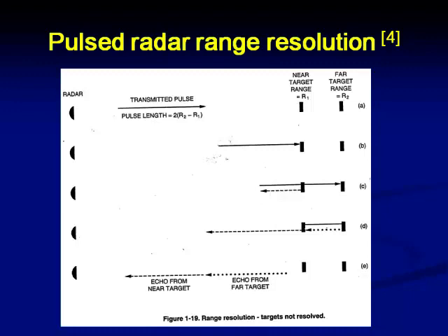So the two echoes are spaced again in a similar manner, and we should be able to receive both of them successively before the start of the next pulse. So for this we have the equation as shown in this. The LP must be less than or equal to 2 times R2 minus R1. So this is the complete picture of this range resolution case.